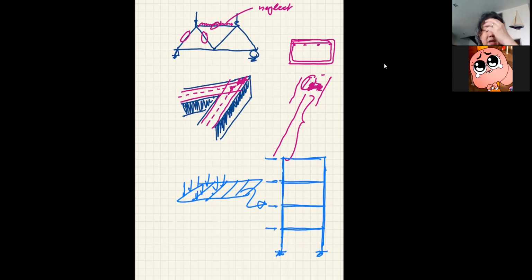And this lateral load can come in the form of wind load or earthquake. So you see, it is very important. And right now, it's a very sad story that some countries, especially developing countries, the third world countries, which have always been poor, construct their houses and small buildings without any system like this at all. They just use the wall, and then they put the beam on them. So there is no system that can resist the lateral load.